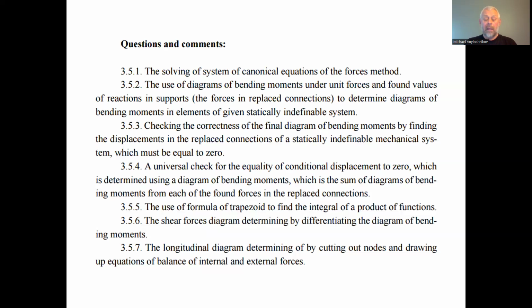So the tangent of the angle of inclination of the diagram of the bending moments corresponds with the magnitude of the diagram of the shearing force. For the linear bending moment diagram, this magnitude of shearing force will be evenly distributed, so constant angle of inclination, constant tangent of this angle.